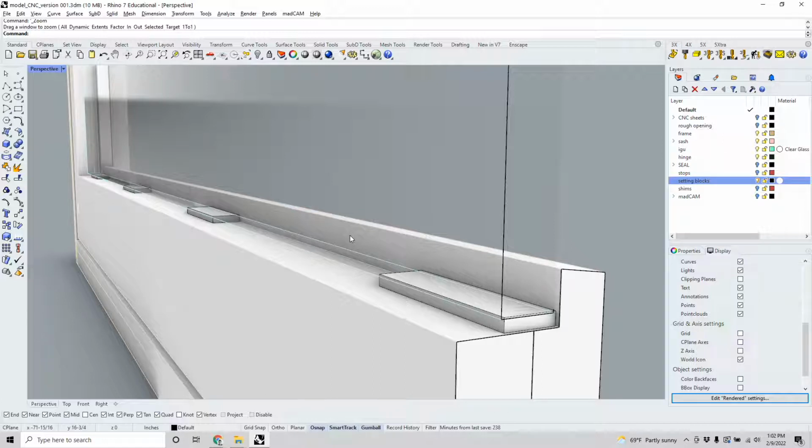Traditionally, solid wood windows are going to contract. That's why you need that gap, right? You need that spacing. But actually, with my plywood construction, the plywood is very dimensionally stable. So I think there's less need for that. But I think it's still very good to maintain that spacing.